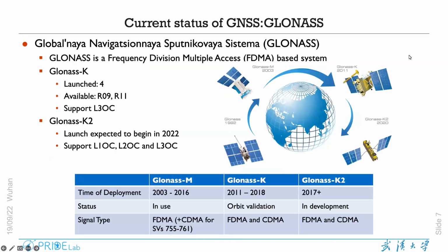And then we come to the GLONASS. The GLONASS signals are quite interesting because they are based on the frequency division multiple access technique. That means for one station on the ground, whenever you receive the signals from the GLONASS satellites, each satellite will have a different frequency, and that will make it difficult for you to process the high precision data, and you will have big problems with the ambiguities in the carrier phase data. We're going to have a brief introduction of the ambiguities later on.